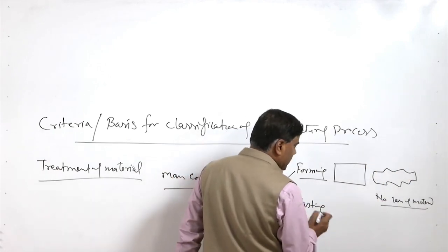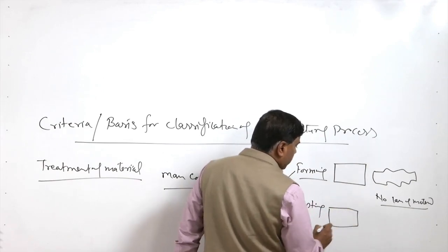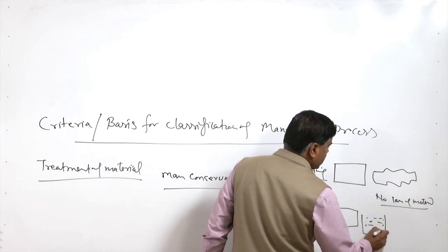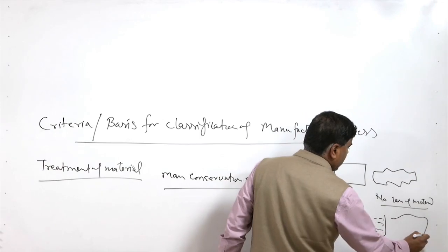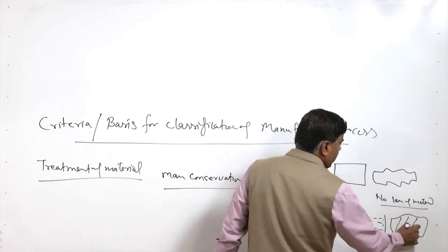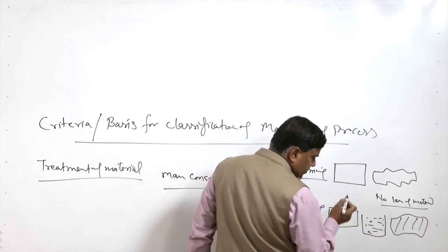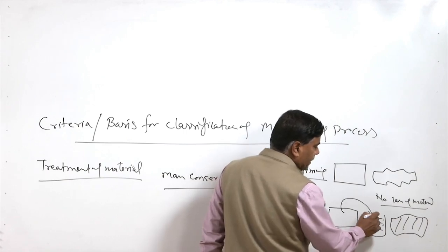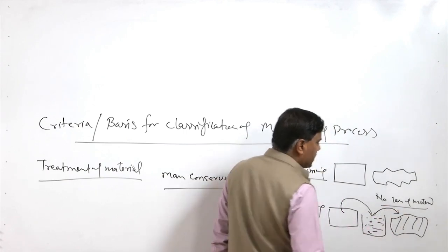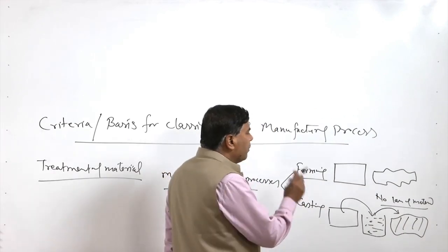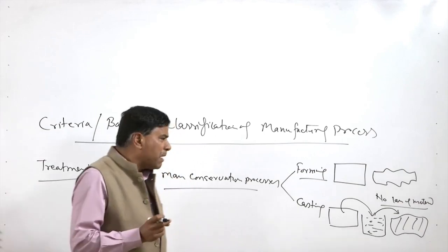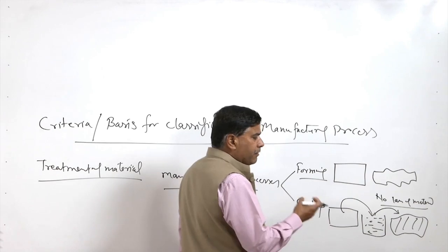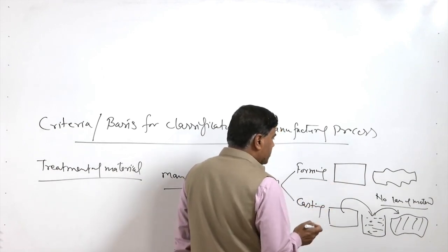Similarly, in case of casting, we take an amount of the raw material and then it is brought to the molten state, and then the same is poured into the mold to get the desired shape of the component. So, the product that we get, only its shape is changed from the initial raw material. It is converted into molten metal and then put into the mold, and the desired shape is achieved. So, technically there is no loss, however little loss may be involved, material getting lost in the form of slag or impurities or oxidation, but those losses are very negligible.